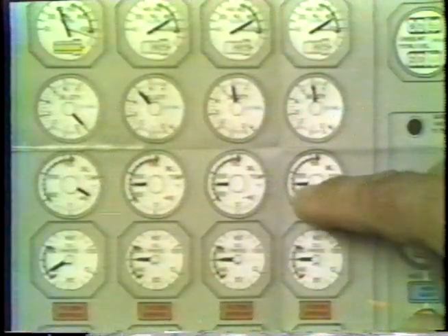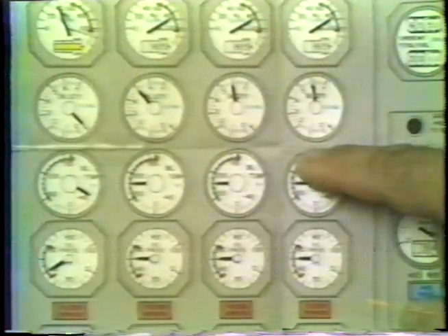By adding thrust the oil temperature will drop slightly until the engine warms up and then come back to normal. Likewise, when pulling off thrust, the oil temperature will rise due to less fuel flow and then come back down to normal. Because of the rise, it could operate in the caution or amber band for a period of time. Of course, anytime the oil temperature gets into the red band, the engine should be considered for shutdown.